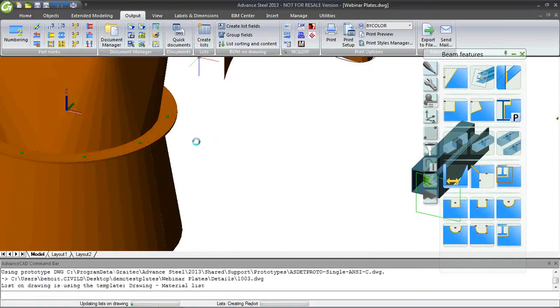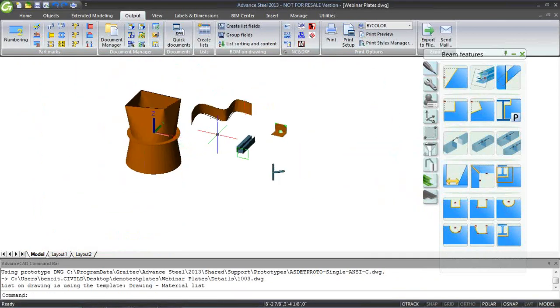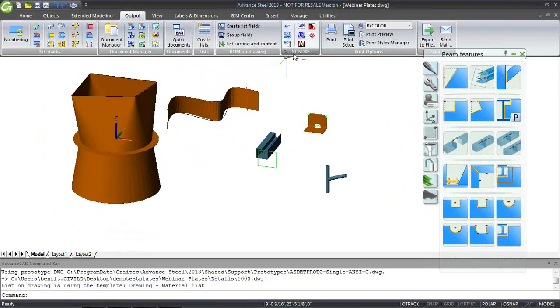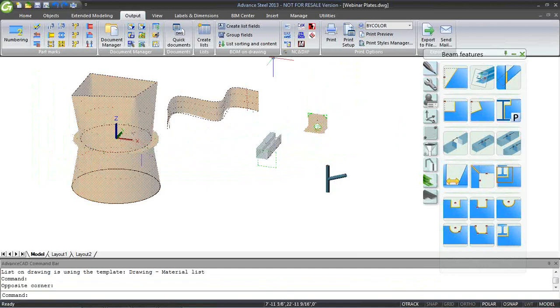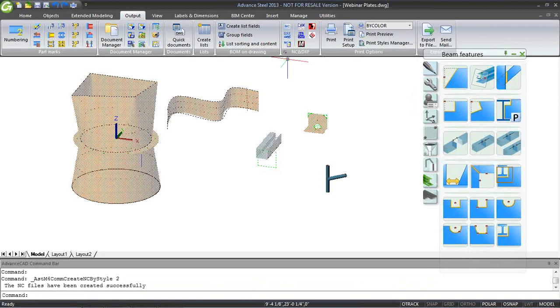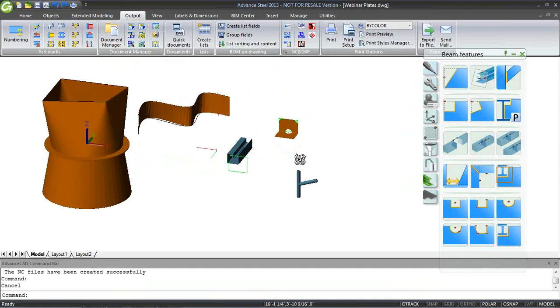All right. So once the drawings are all done and created, we could run also the DXF. We have great options here for creating DXF for plates. We would just go and create a selection of those plate works, and creating DXF options plates would be coming from here. And we'll see in a few seconds where those drawings are going, where the DXF plate information is going. We'll find this under our Document Manager.